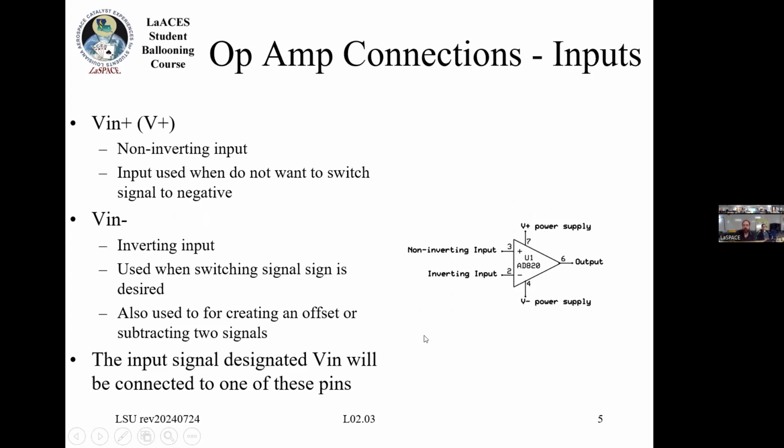Usually when you're building one of these circuits, you have some input signal, you call that V in, and that's going to be connected to one of these things. But typically you don't have two V-ins unless you're doing the case where you're actually subtracting the difference between those two circuits.